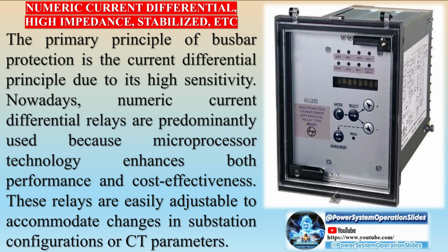Several types of BFP schemes exist, and they typically rely on the occurrence of two signals within a specified time frame: an external start signal and confirmation of an overcurrent condition, or alternatively, a circuit breaker contact signal. The external start signal is usually triggered by a trip command from any protection function, such as a distance relay or a differential relay, depending on the type of feeder.